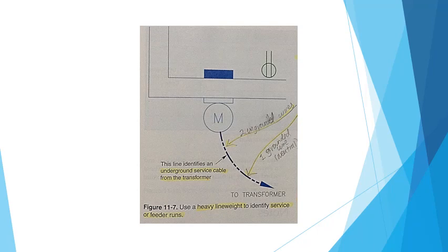If every circuit were drawn and installed as installed, the lines would continue to the circuit breaker panel. To prevent this buildup of lines near the panel, the circuit line is not drawn all the way back to the panel. Instead, the circuit line stops at the point where the run back to the panel begins. This is called the home run.